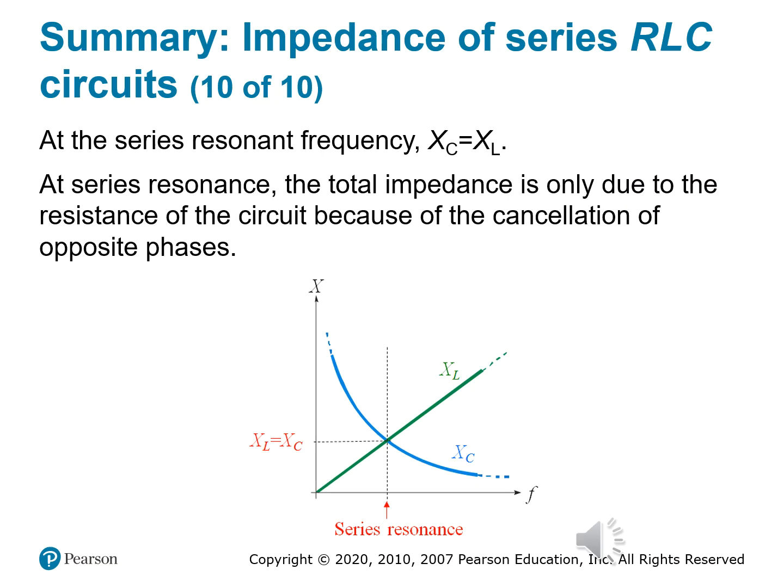Remember, we said X sub C is equal to X sub L. Inductive reactance is perfectly equal and opposite to capacitive. And because they cancel each other out, the circuit's impedance isn't influenced by reactance anymore. It's just purely resistive. That means the total impedance of your RLC circuit is now just R, nothing more.